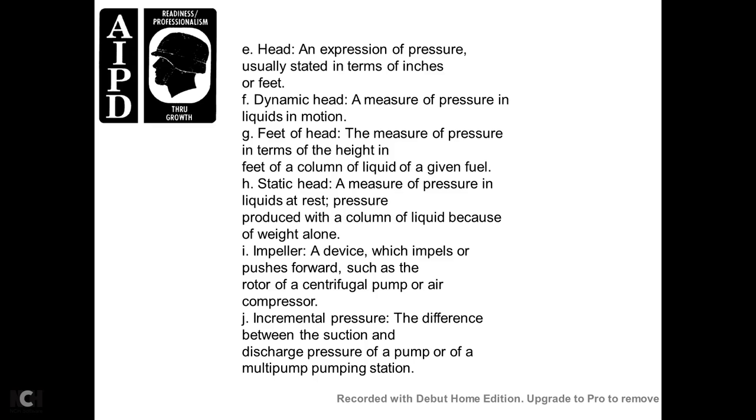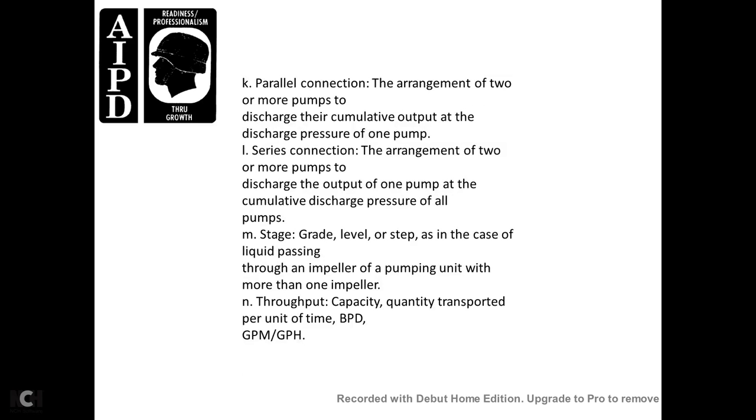Static head: a measure of pressure of liquid at rest, the pressure produced by the column of liquid because of its weight alone. Impeller: the device which impels the push forward, such as the rotor of a centrifugal pump or air compressor. Incremental pressure: the difference between the suction and discharge pressure of the pump in multiple pump stations. Parallel connection: the arrangement of 2 or more pumps discharged with the cumulative output of the discharge pressure of one pump. Series connection: the arrangement of 2 or more pumps where the discharge output of one pump feeds the next, with the cumulative discharge pressure of all the pumps.